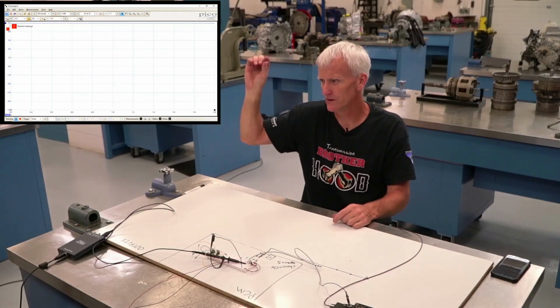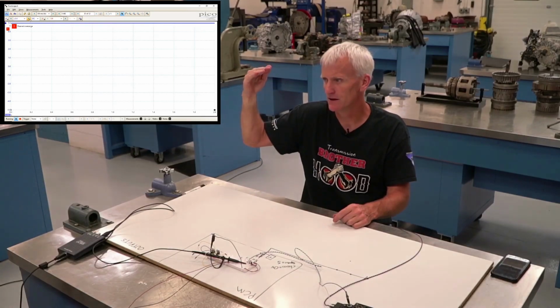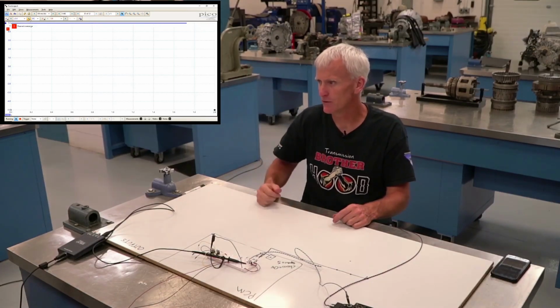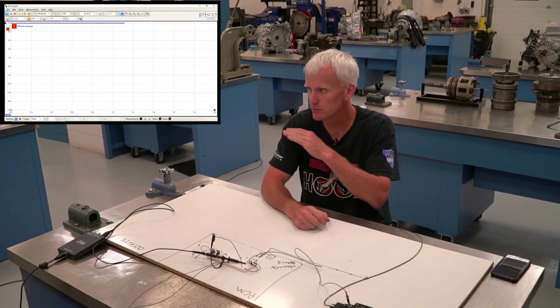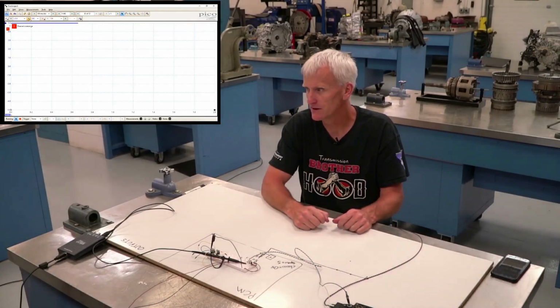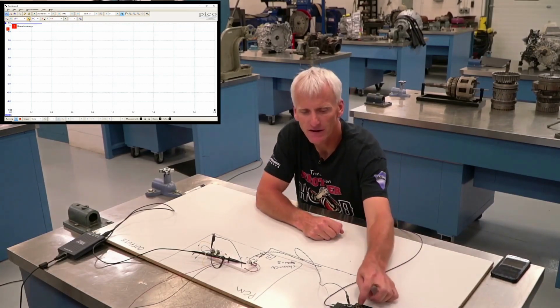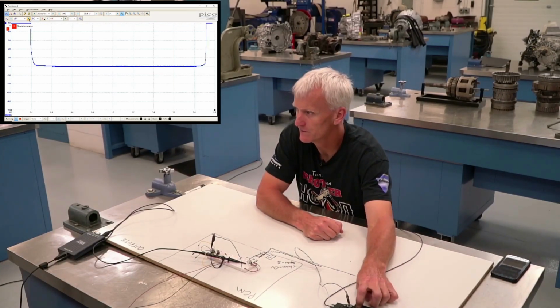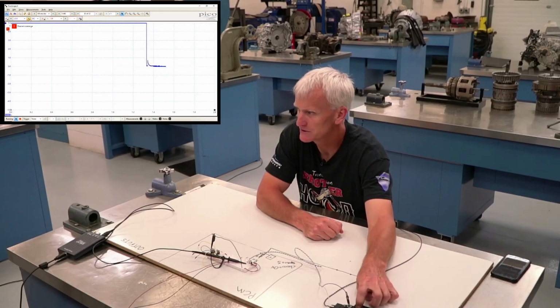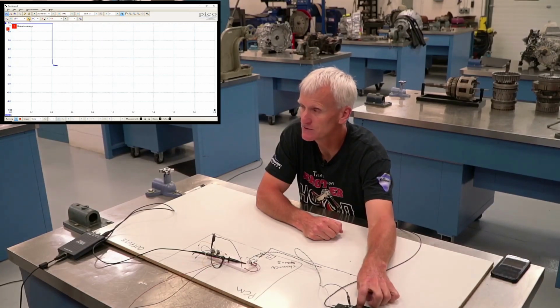It says channel overage because I'm on a 5 volt scale and it's just kissing that 5 volt mark. So I guess noise and so forth is making it go over voltage. But you can see the blue line cruising there at 5 volts. Now if I find whichever switch it is that grounds the circuit out, oh, right there. If I imagine pressure pushes down, now the voltage drops to 0. And you can see I can make it go up and down just by pushing on that switch.